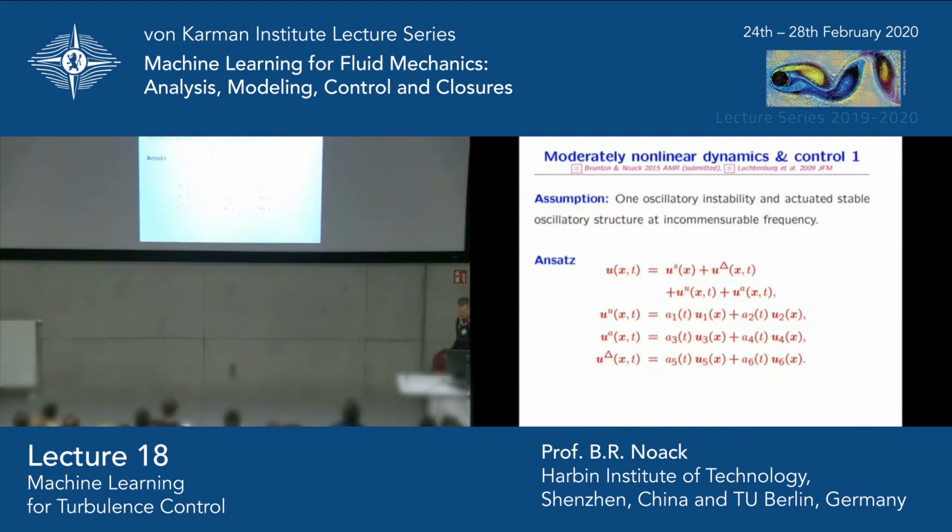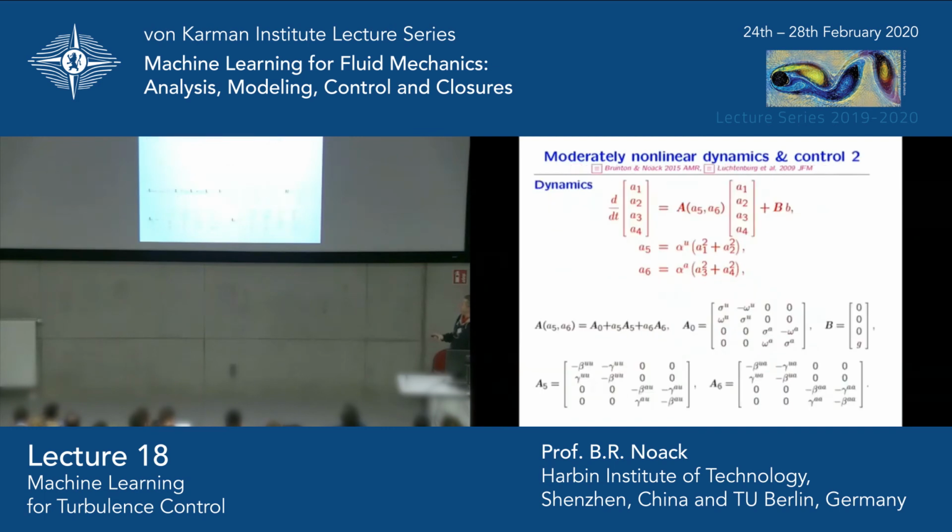Good. So the general approach, just a recap: you have a steady solution, base flow deformation, and a component from unsteady vortex shedding from your actuation. So these are the two frequencies. First frequency, second frequency, you always need two modes. Each of the contributions has one corresponding shift mode, a Reynolds stress contribution. So you always end up with 6 modes, and you can show that the general structure of the dynamics derived from harmonic balance and so on looks something like that.